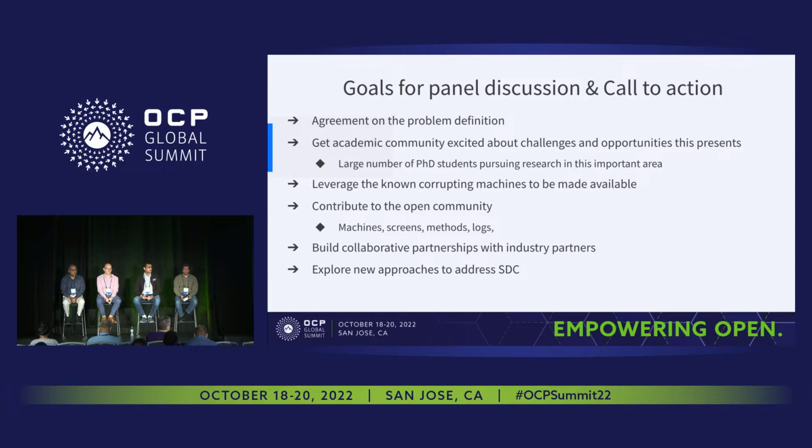For every chip that escaped, for example, manufacturing tests and whatnot, and got detected later in the field, I would like to see a database, of course anonymized, with no confidential information, about what chip was that, a processor or something else, under what conditions did it pass in manufacturing test, and under what conditions it failed later on, and if there was a root cause analysis done on that chip or not, and if the root cause analysis was done, what was found? Was it a bridging fault, or was it an open, or what?